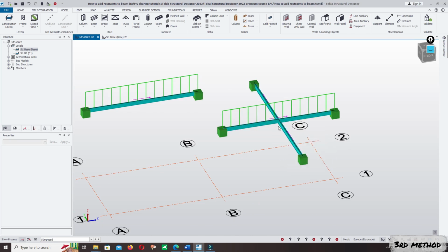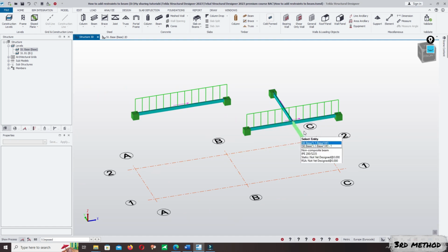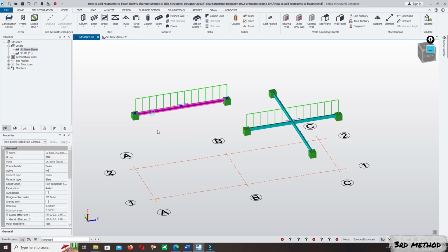There are two sub beams intersecting the main beam at lengths 0 meter, 3 meter and 6 meter, at the center of the main beam. So it's similar to this beam. When you model a beam without a sub beam, you can edit the option during modeling to correct the lateral torsional buckling factor on the main beam.